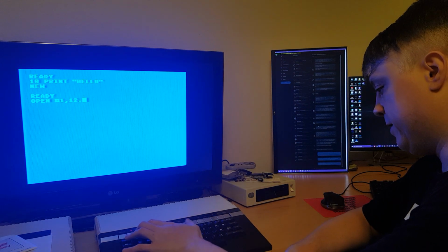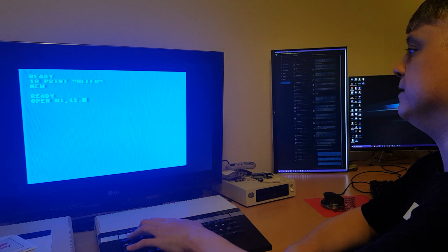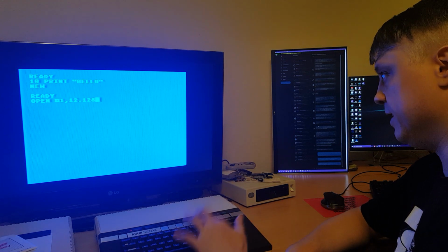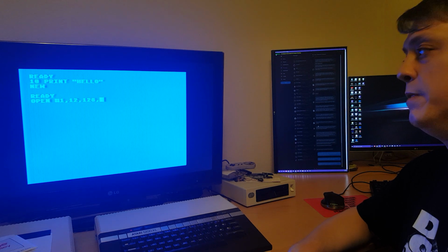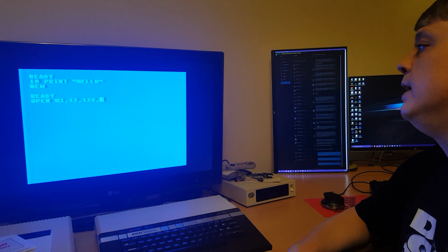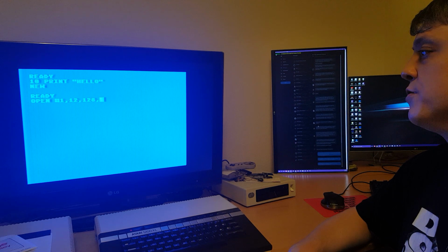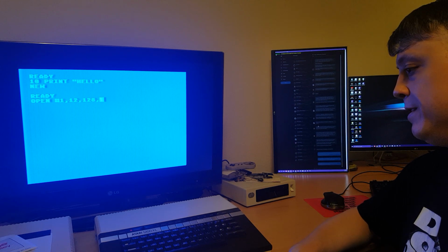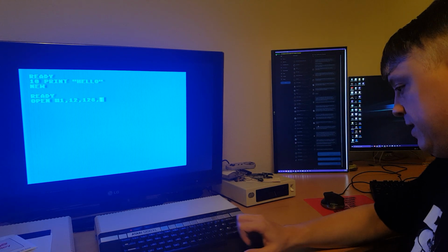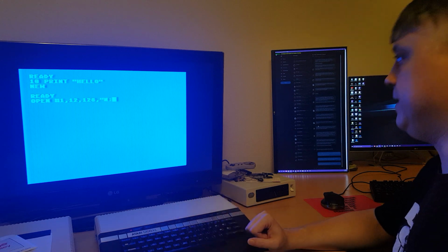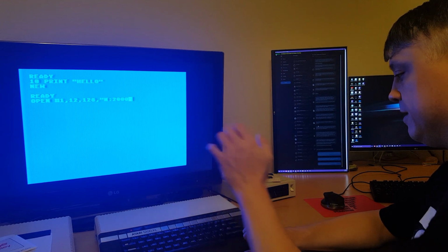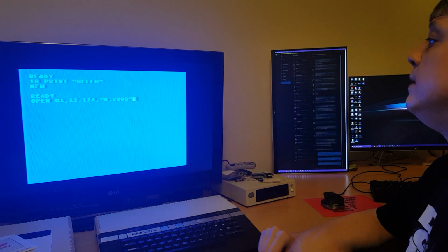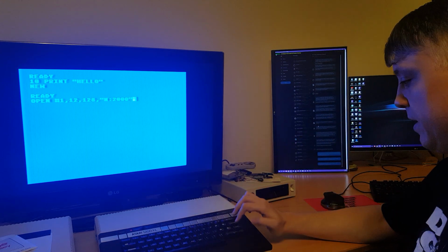But we actually use aux2 for various different things here for network control, and one of these things is bit number 8, or bit number 7 if you're counting from 0, which controls whether this is a listening socket or not. And if this is a listening socket, you need to specify the listening device port number, but you also need to specify what port you wish to listen on.